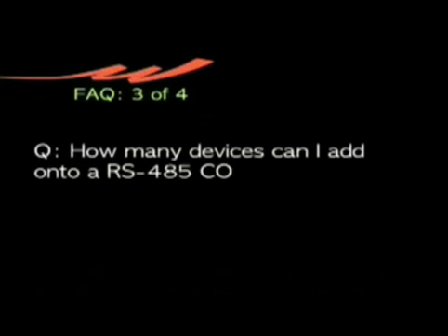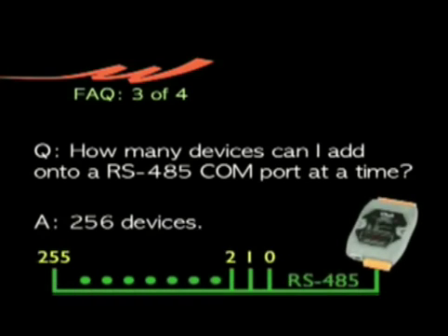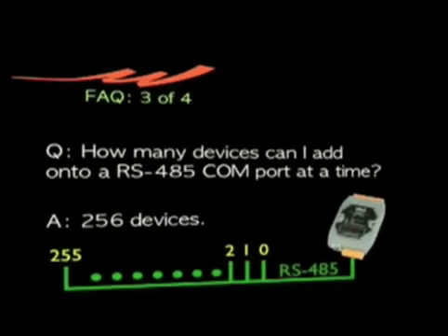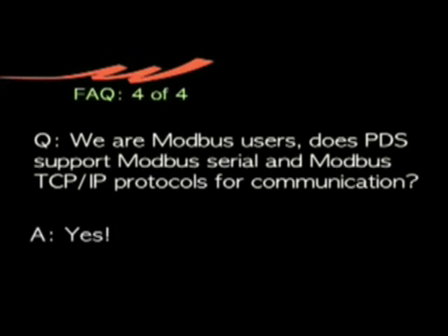How many devices can I add onto an RS-485 COM port at one time? You can add up to 256 devices. We are Modbus users. Does PDS support Modbus Serial and Modbus TCP/IP protocols for communication? Yes!